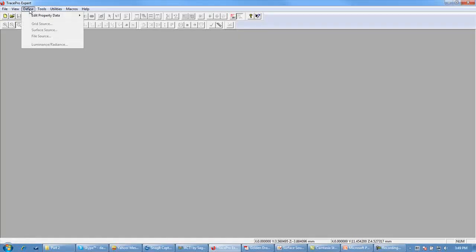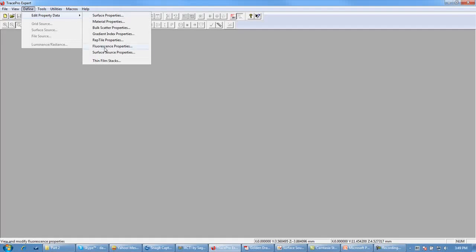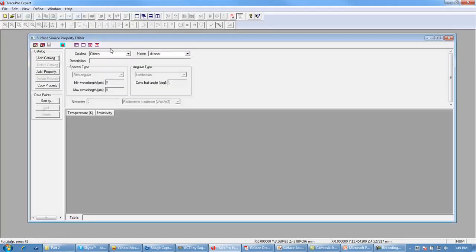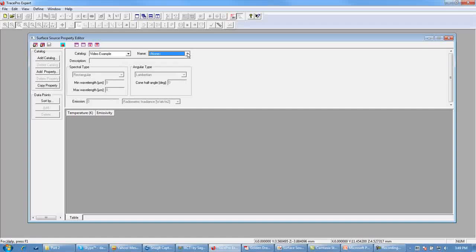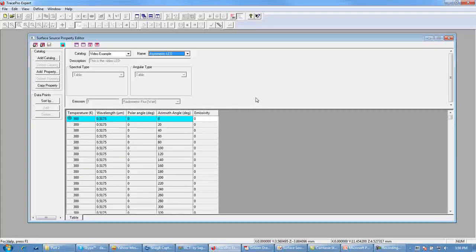If we go to Define, Edit Property Data, and Surface Source Properties, we can then go to the catalog that we created, in this case Video Example, and we can come down to the property that we made, Asymmetric LED. We see our description here. This is the video LED that we entered in when we exported the property. Here's our polar and azimuth angles, our wavelengths, and our emissivity definitions for this property.